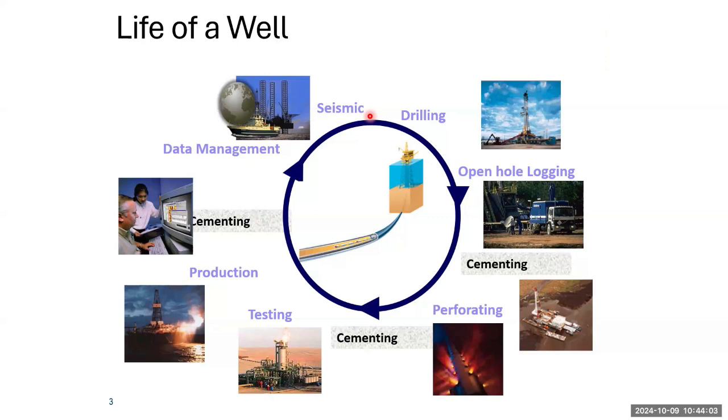He has another question, and he asks, can we use sand or gypsum instead of cement slurry? And what is the best productive well bore depth? Sand is used not in cementing, it is used for certain other operations, like, for example, hydraulic fracking. You need to have certain characteristics of this cement, right? You need to have a certain yield strength of this cement. Sand does not provide you that yield strength. It needs to have a certain setting time, needs to have a certain temperature resistance. Cement, which is a Portland cement, will actually afford you with all these properties. Gypsum or sand, on the other hand, will not afford you all these properties.